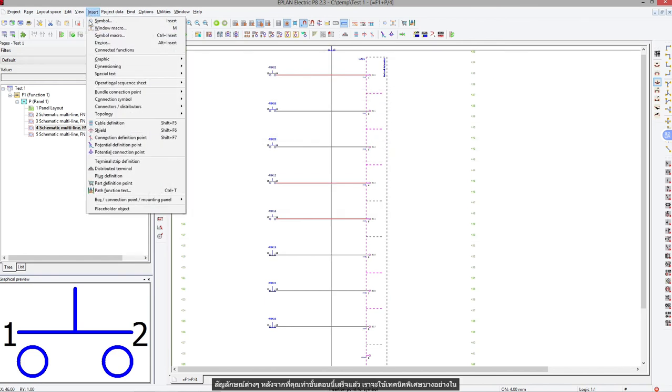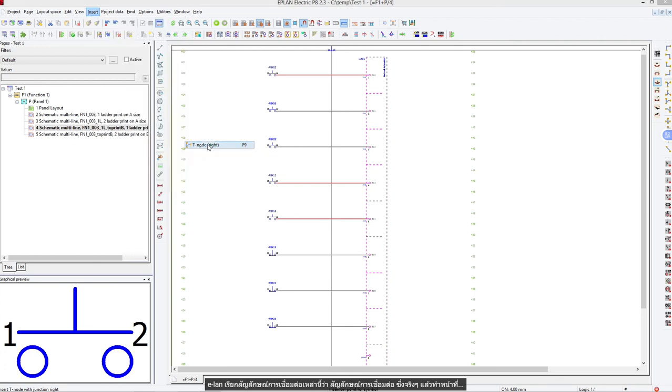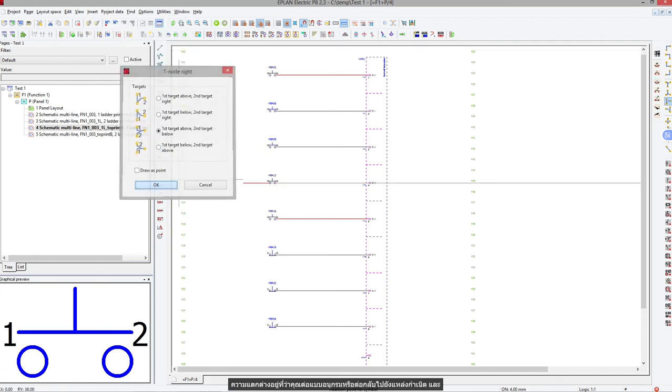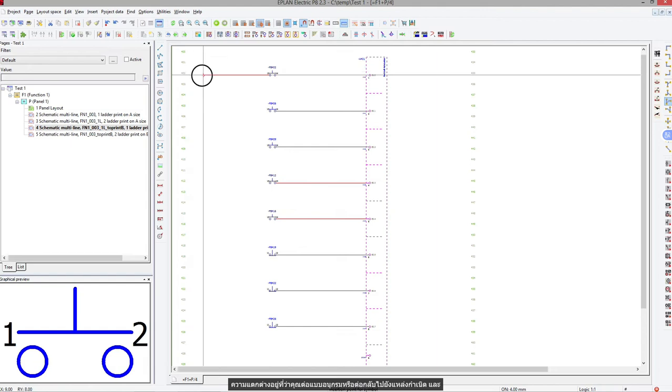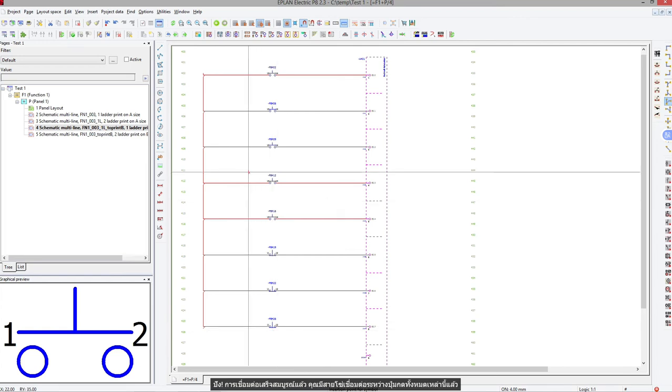After you've done this, we're going to use some special tricks in EPLAN called connection symbols. These connection symbols actually make the difference whether you have a daisy chain or back to the source. An interesting thing is when you pull them down like this, just drag and drop, boom, the connection is done. You have a daisy chain between all these push buttons.